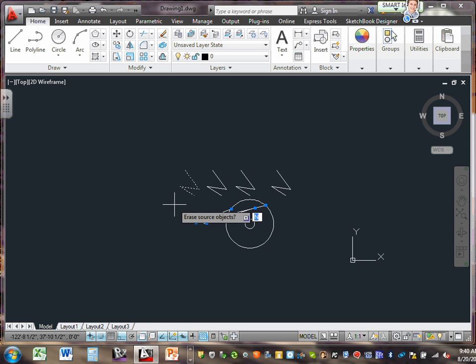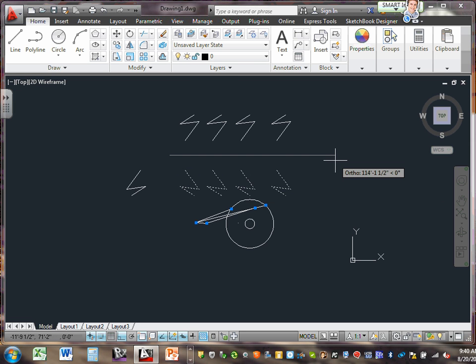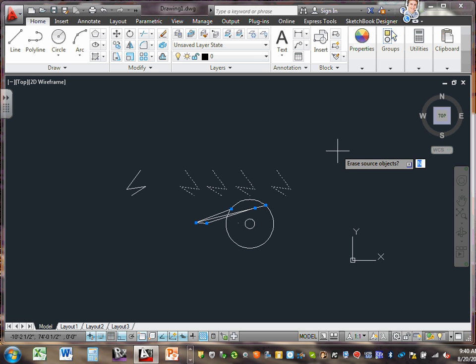Okay, ortho. Enter. There you go. You have to hit enter at the end, after the direction that you want to mirror. So I'm going to flip these. Right click, click here all the way, then hit enter. Okay. Click, hit enter. Yeah, you have to hit enter at the end, and that will flip it to the other end. I wasn't hitting enter. Were you guys able to mirror things? Do you see it's handy? It's a handy tool.